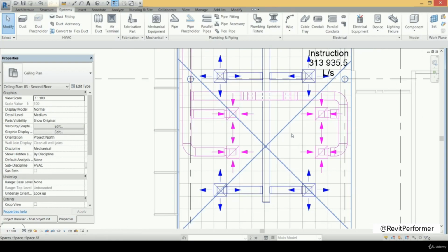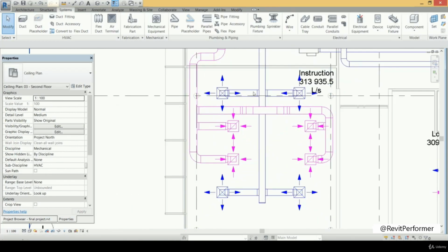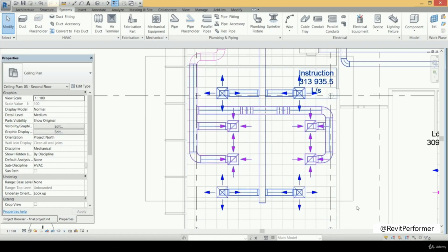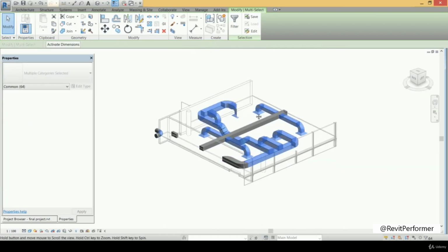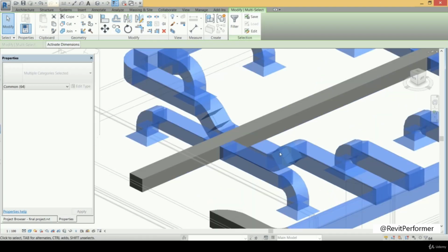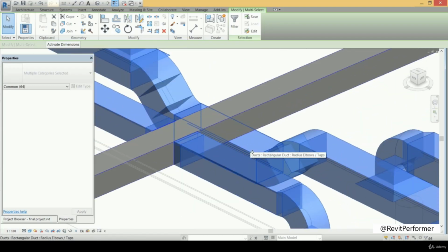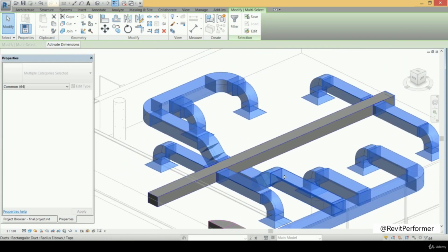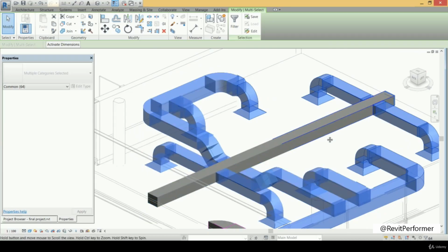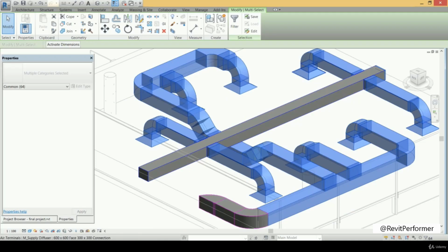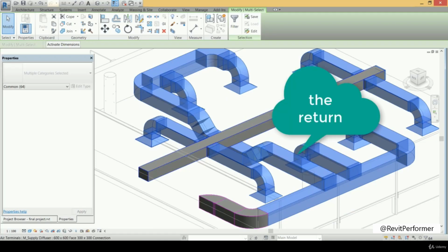More than great. Here, by that way, we have managed to connect the return ducts that we have to the return diffusers. And if we see that part in 3D form to imagine it whole, that's good. You can find that this is the offset that we have changed to 2750 millimeter. And this is the original offset, 3150 millimeter. So this is to overcome that supplying duct. And those are the two other diffusers that we have. And those four diffusers, that one and that one, and the third one and that fourth one, are the supplying diffusers. All right, now let's close that.